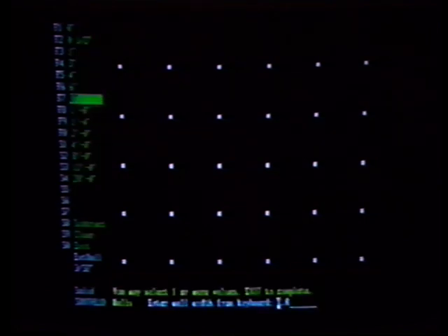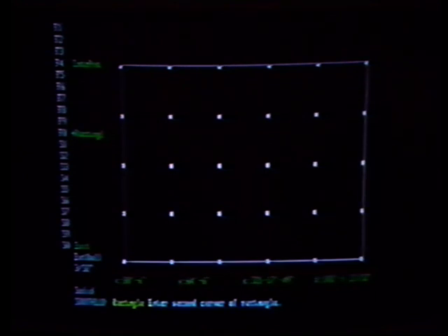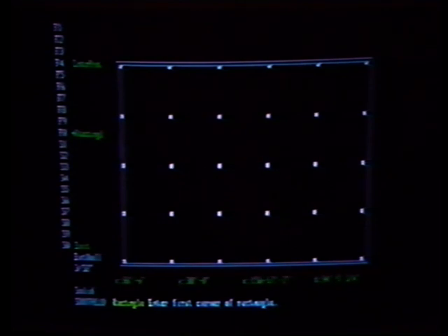Once I have the column grid in, then I can go in and put in the exterior wall of the building. To do that, I go back to the DataCAD AEC menu, to the next menu down, and choose Walls. Here I'll set a wall width of 1 foot, and we'll create the wall by making a rectangle around the outside of this column, and what you're seeing here is DataCAD's automatic save function saving the drawing as I go. So in the event of a power loss, all my work is saved. There's the wall that we've created.